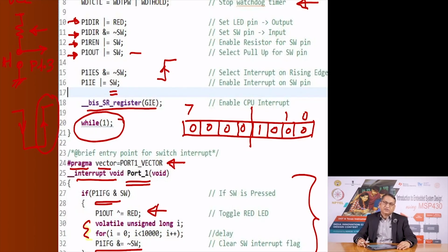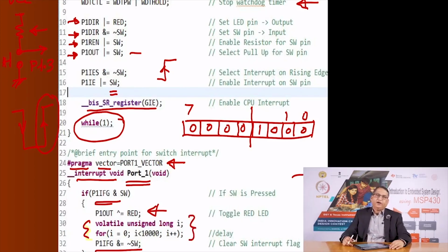And why do we call this example of an interrupt subroutine not a good example? Because we have used a delay subroutine. We do not recommend using delay subroutines in the interrupt program. Now, how do we deal with this? Well, make sure that you do not have to debounce your switch. Now, if the switch is read using polling, this is a good method, but reading a switch or debouncing the switch using delay in the interrupt is a complete no.